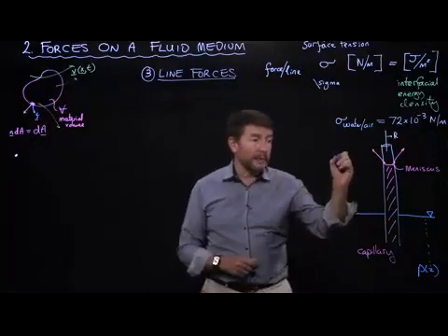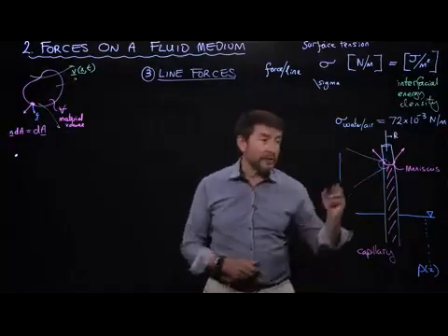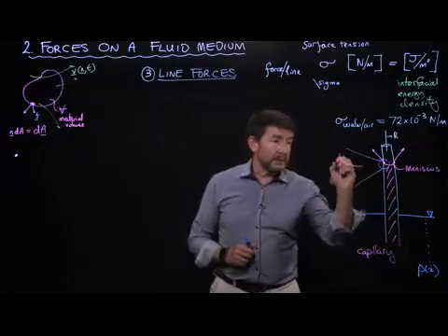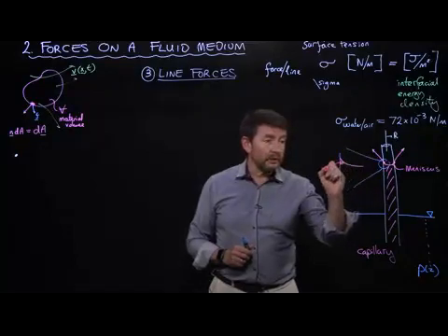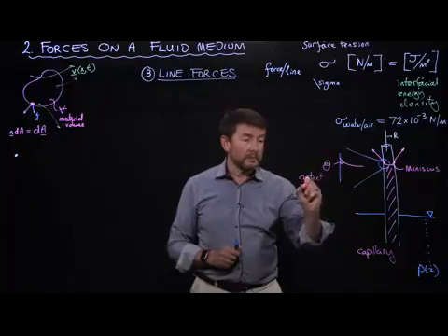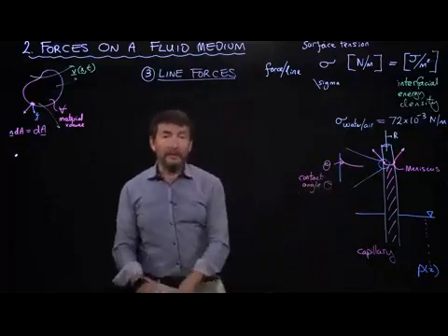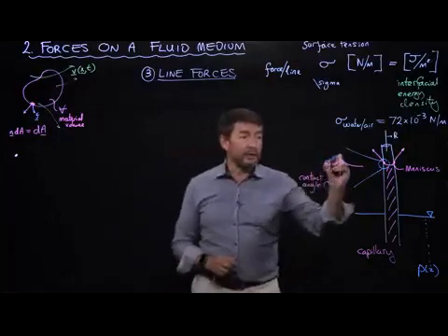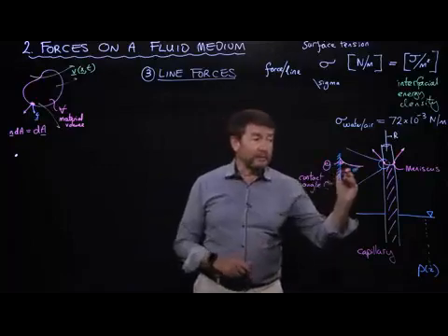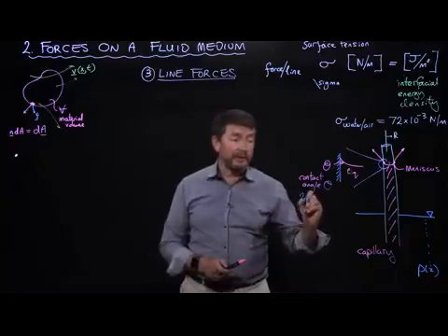So if we were to zoom in on this region, we'd find that locally the liquid has formed a shape where it has adopted an angle, and this angle is usually called the contact angle theta. And this is a boundary condition that sets the shape of what's going on at the boundary between a solid material and our liquid material. So we have a liquid here, we have a solid here, and so this is an example of a two-phase boundary condition.